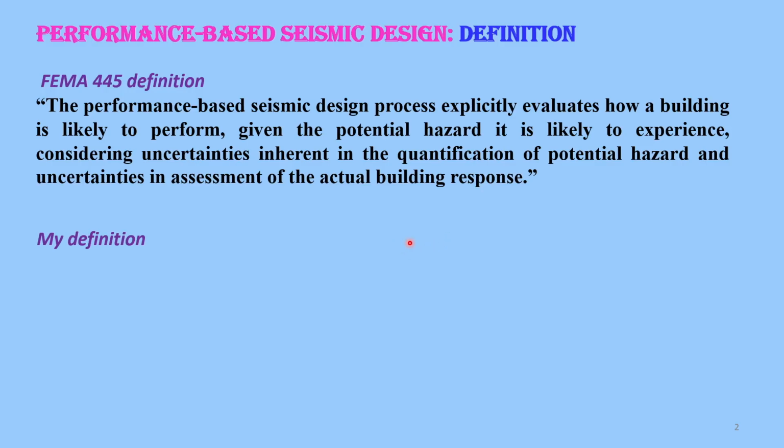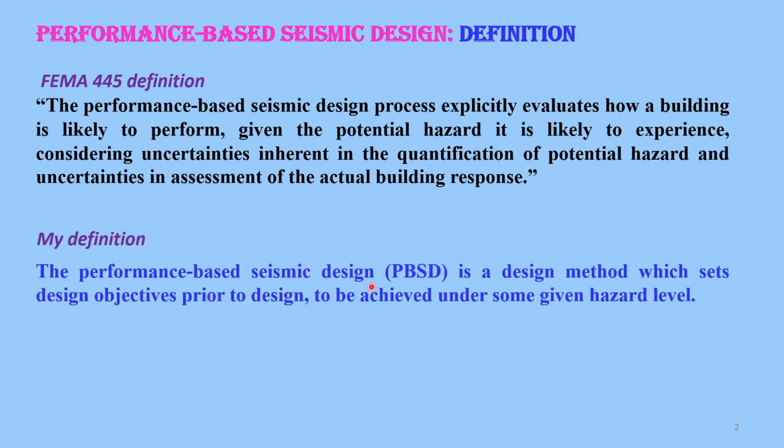Okay, I give a small definition here. The performance-based seismic design is a design method which sets design objectives prior to design, to be achieved under some given hazard level. This definition is simpler. We have some design objectives which are set prior to the design, which is not done in the codal design methods, and this is to be achieved under some given hazard level. The hazard level you can take to your requirement, and the design objectives also you can set to the requirement of the customer or the functional use of the structure.